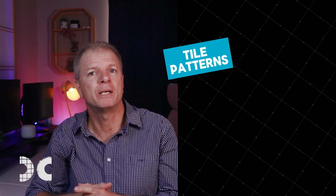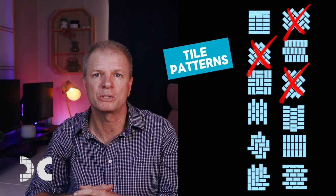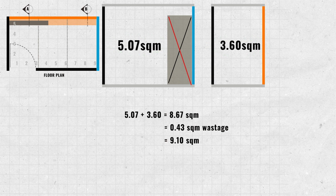Search tile patterns and consider the many options, however steer clear of angular options as they will be slow and more expensive to install and generate more wastage. Now I'll draw the walls in elevation, calculate the areas, subtract for windows and doors, then add 5% for wastage. These areas will be rounded up further to account for ordering full boxes of tiles.